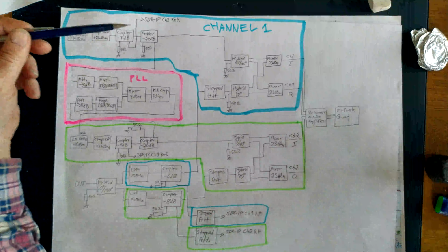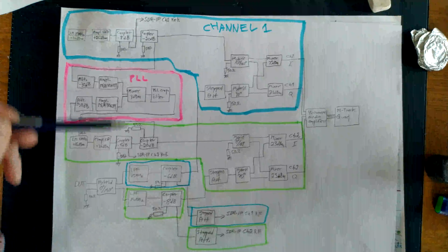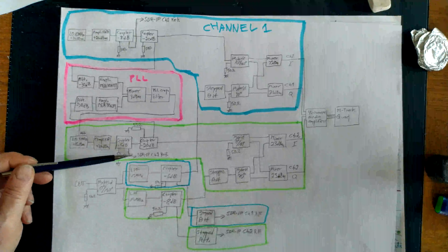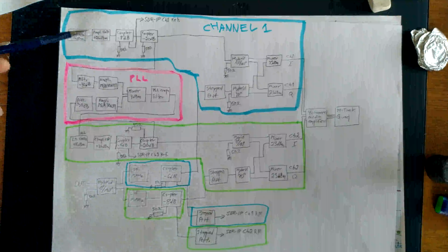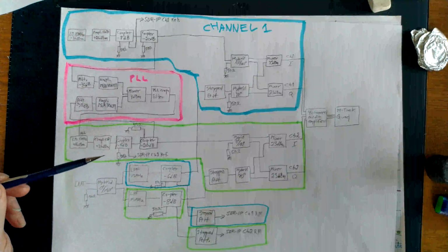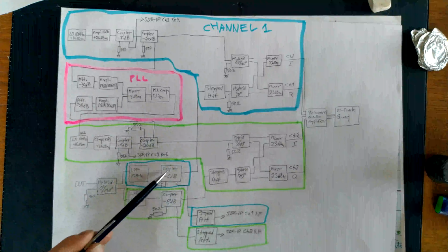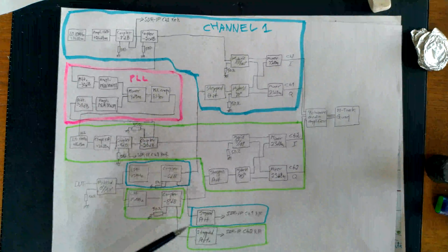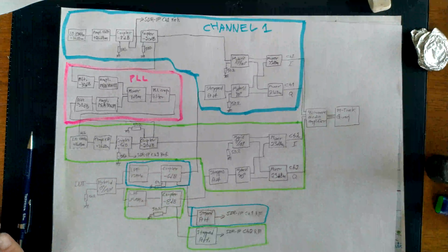And at the same time I take out this reference signal from one oscillator and from the other oscillator to use as references for the SDR-IP units. So they are locked to 10 MHz, but they don't share the low frequency noise from these reference oscillators. Not until the frequency is below 0.1 Hertz or something like that. And then I have couplers to take a part of that signal that goes this way to put into the SDR-IP units. So that is the measurement system that I'm using now.